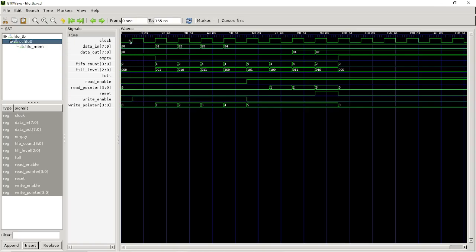But normally when you're designing RTL, you should have a reset. You should provide reset in the beginning because that's how we design. So this is the part that I think ChatGPT missed. We should have done maybe several clock cycles worth of reset right up front, and that is something I would have done. Then there's obviously the writes happening in the beginning.